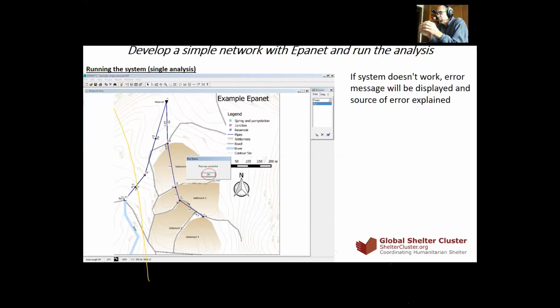Then it's like if you start to run the system with no water in the tank. And then, of course, if there is no water in the tank, at the very beginning, no water is flowing down. So you will have a very high negative pressure. So at the very beginning, when you run this first single analysis, put some water in the tank upstairs, 1 meter, for example.